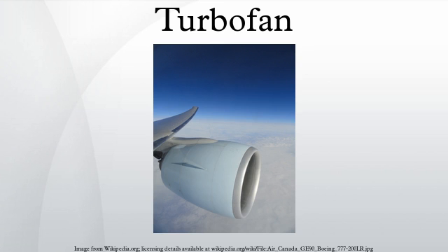Single-shaft turbofan. Although far from common, the single-shaft turbofan is probably the simplest configuration, comprising a fan and high-pressure compressor driven by a single turbine unit, all on the same shaft. The Snecma M53, which powers Mirage fighter aircraft, is an example of a single-shaft turbofan. Despite the simplicity of the turbomachinery configuration, the M53 requires a variable area mixer to facilitate part throttle operation.